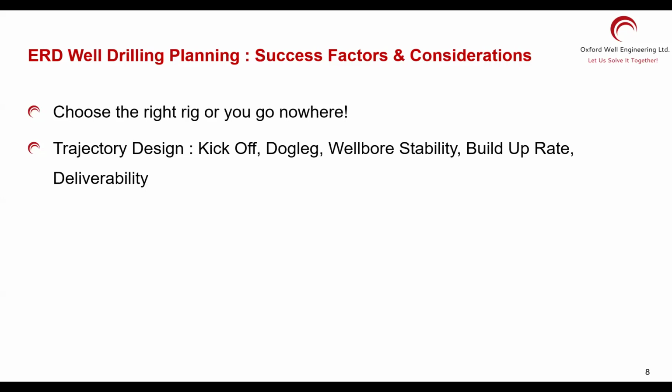Okay, so let's take you through to casing wear. ERD brings casing wear. A lot of them have a casing wear problem. If you don't pay attention, it can eat into your casings, and then you have no well. When you have destroyed the casing because of the casing wear problem, a well integrity problem comes in.